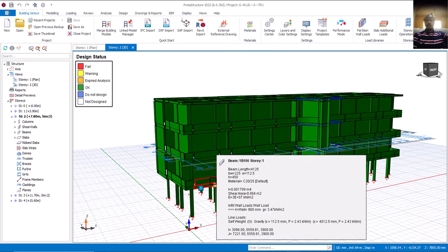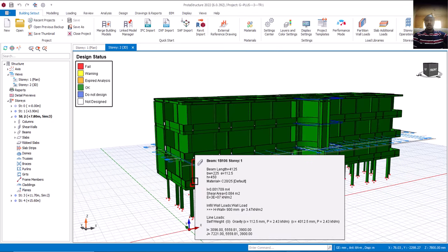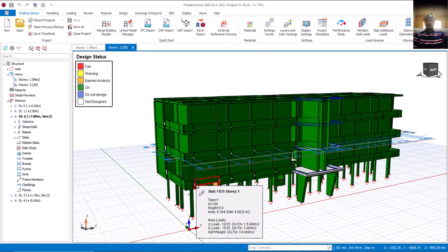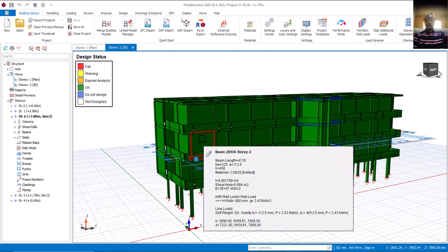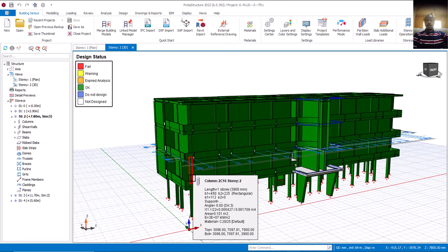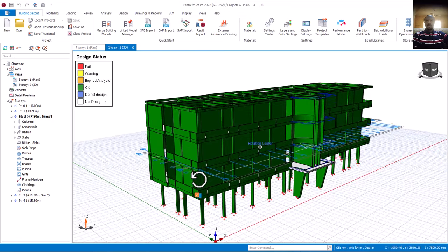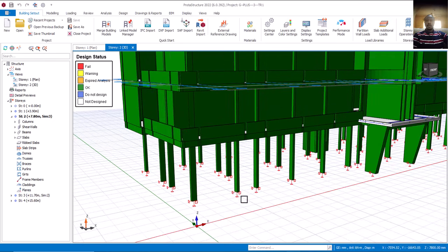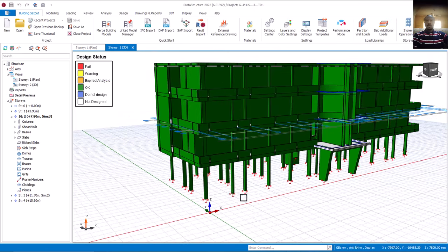And the kind of height we are talking about, each floor is about 3.9, almost 4 meters. From this ground floor to this place is about 4 meters. From here to here, 4 meters. From here, 4 meters. So you can imagine the height of 4 meters and the kind of load from your block walls. Definitely pad footing will not really work.